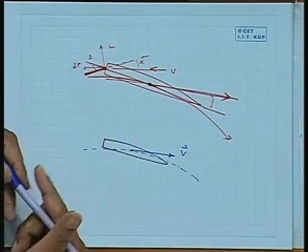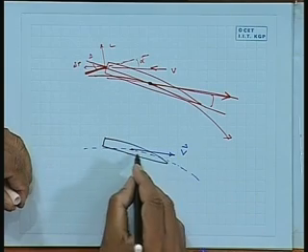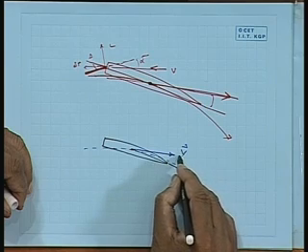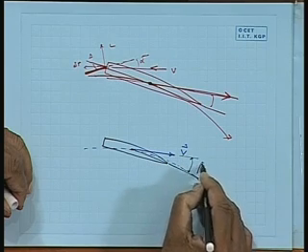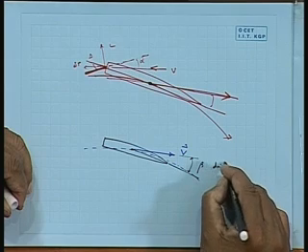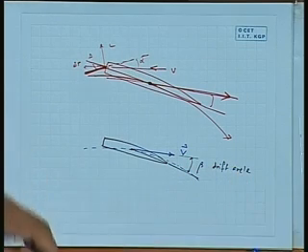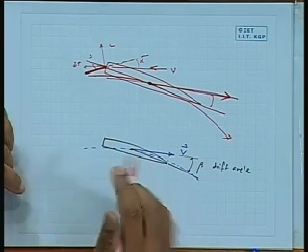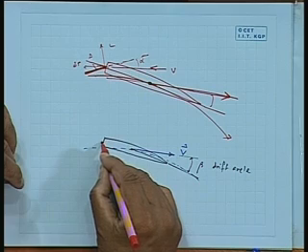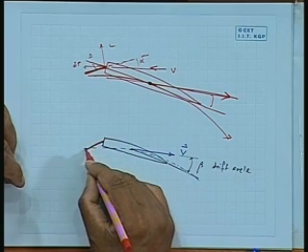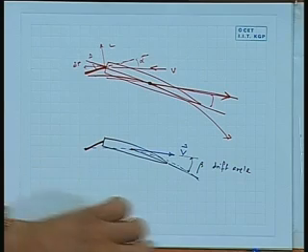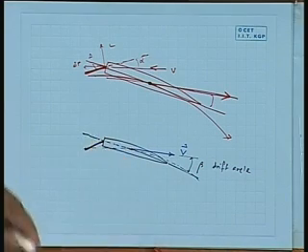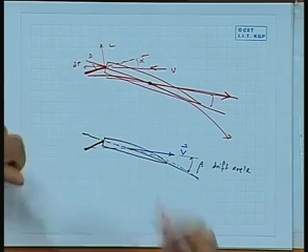Okay. This is my longitudinal axis of the ship. So, as far as the ship is concerned, we are calling this the drift angle beta. All right. Just see this point by point. Now, this was turning because the rudder was in this direction. So, what is the rudder angle? The rudder angle is obviously the angle it makes with respect to the ship, that is, this angle is my rudder angle.